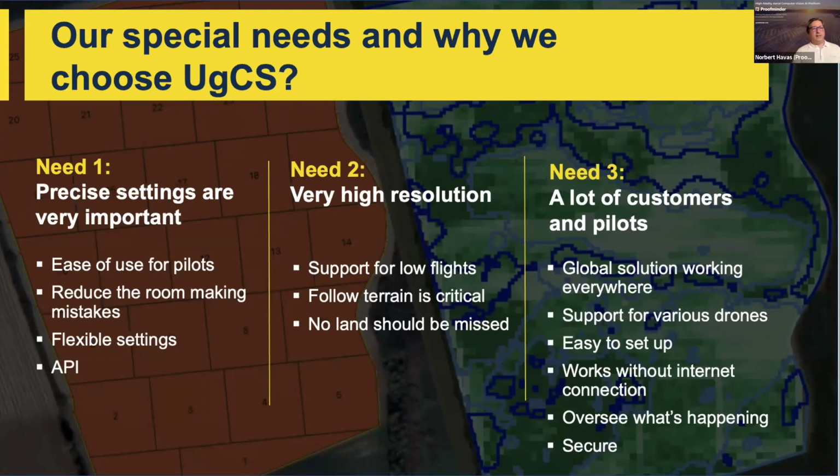First of all, we have very rigid settings. When we want the pilots to capture the data, then we give quite a lot of settings and details how they should fly, whatever elevation, what camera angle. We don't always use the camera to face down. Sometimes we use a pitched camera angle. We have to make sure that we capture everything on the land and we don't miss a couple of meters when we design the flight.